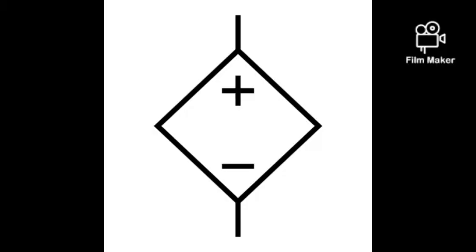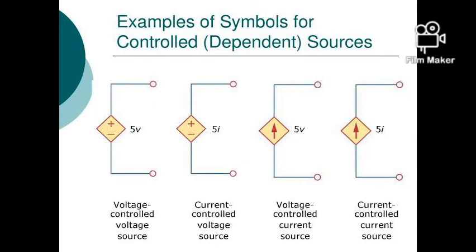For the dependent power supply, this symbol is used to denote the voltage source, and that symbol is used to denote the current source. Due to their dependency, they can be controlled by the voltage or the current from the independent source. Because of that, they are classified into four, which are the voltage controlled voltage source, the current controlled voltage source, the voltage controlled current source, and the current controlled current source. This classification is based on the ability to respond to certain adjustments by the external voltage or external current.